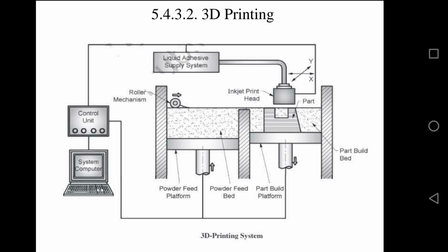These regions of powder are bound together by the adhesive at the locations where it is printed, as per the information from the 2D cross section. The remaining free powder supports the part during the build process.